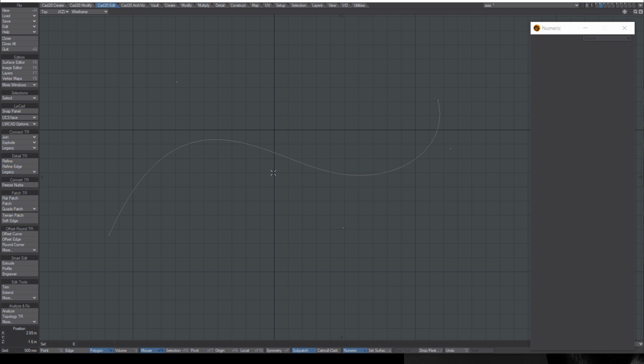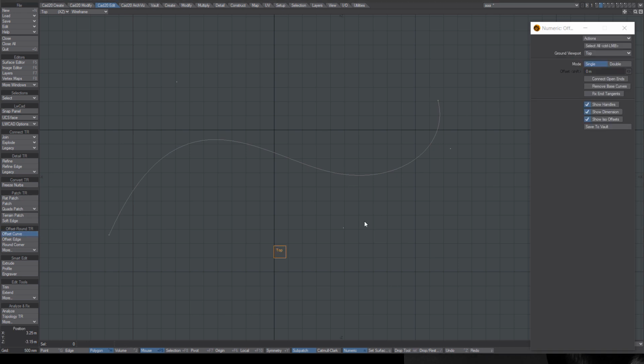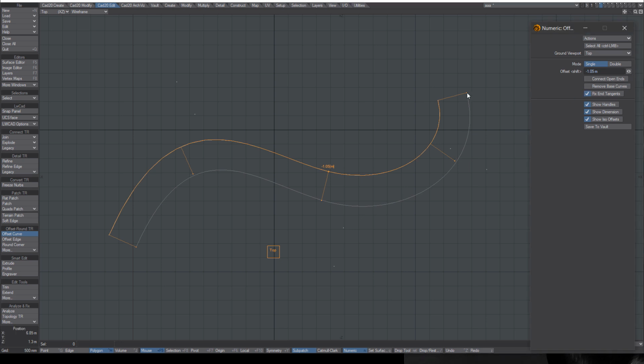The precision of offset operation depends on how many control points you have per NURB segment. If you have a small amount of control points and the angle between these control points is too high, then you get bigger error. You have three ways how to control this. You can switch between precise end tangents and precise ISO offsets. So if you enable fixed end tangents, then end tangent of the offset curve will be precise with original curve, but ISO offsets there will be error. If you disable this, then the ISO offsets are precise, but the end tangent of offset curve is different from original.